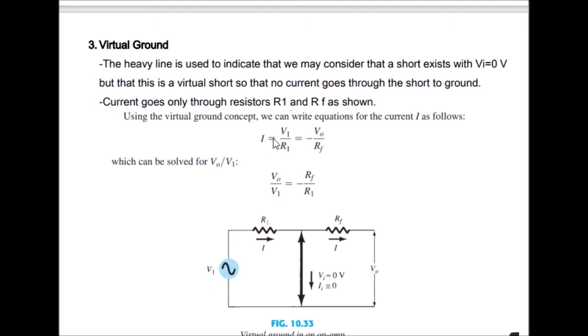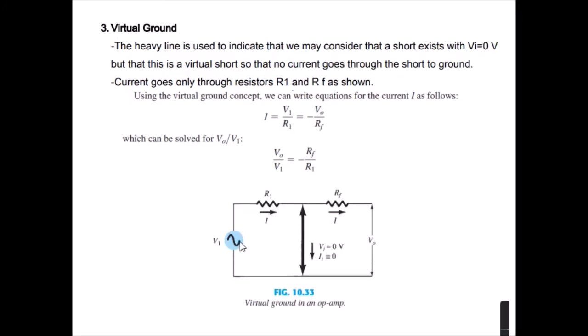How is that possible? I times R1 is equal to V1. Why? Because since as if may short ka dito, class, pero walang current, but then short, kung titingnan mo, 0 voltage drop dito, di po ba? Kung titingnan mo, you can have here loop. And since dalawa lang sila, yung V1 mo is just equal to the voltage across this R1 resistor. And kung kukunin mo yung current, of course, your I is equal to V1 over R1.